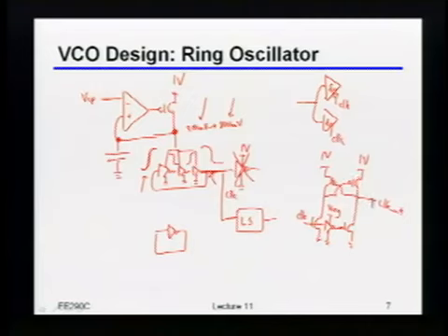In contrast, to make this go low, I have to go through this inverter, which is on the regulated voltage, then turn on this NMOS and pull that node down. So the delay from those two paths is completely different. Even at just 1 voltage it'll be wrong. If you change that voltage around, it'll move around in terms of how wrong it is.